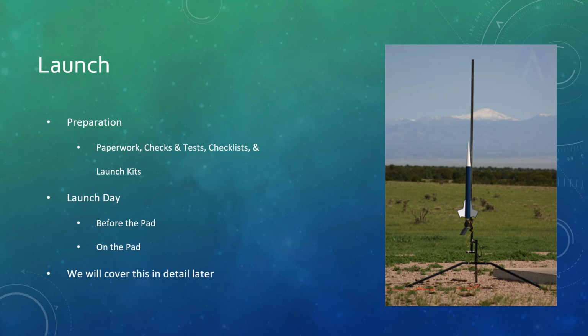So once everything is all set, you want to activate your deployment electronics. Make sure that they are properly activated. If they're, for example, Stratologgers, they'll beep at you. Then you just head back, get ready to take some video, and cross your fingers.